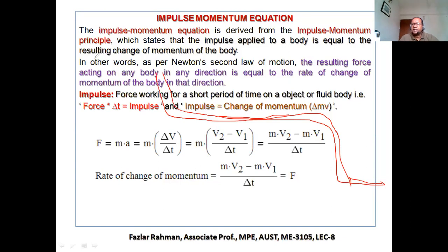Its momentum is changed because momentum is mass of the fluid times velocity, right? And velocity is a vector quantity. So you see right over here, fluid entering in this direction, then it changes 90 degrees in direction. That means the velocity might change direction and also magnitude depending on the diameter of the pipe.